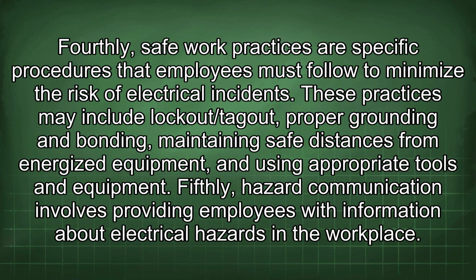Fourthly, safe work practices are specific procedures that employees must follow to minimize the risk of electrical incidents. These practices may include lockout/tagout, proper grounding and bonding, maintaining safe distances from energized equipment, and using appropriate tools and equipment.